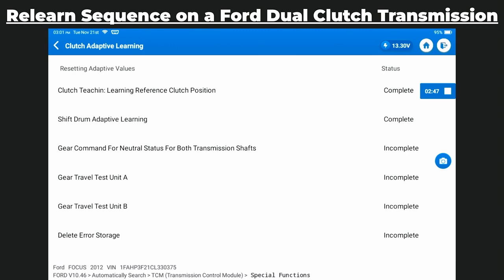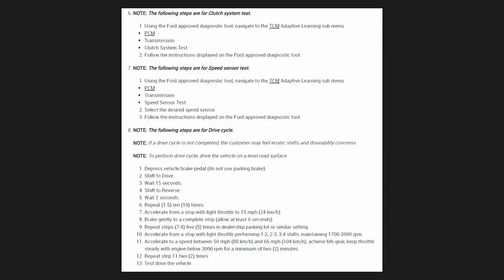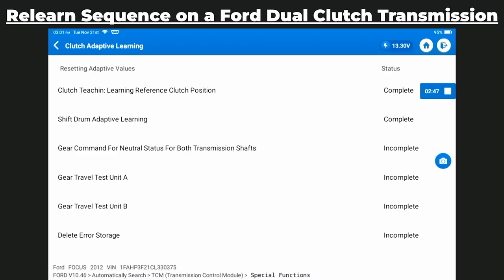You can see here that it's only partway through the procedure on this screen, and we could reference all of the steps back in the written information from Ford in order to figure out what total number of steps have to take place before the transmission control unit is happy and ready to resume normal operation again. Anyhow, just wanted to show you what the Relearn Steps screen looks like as it is going through the process.